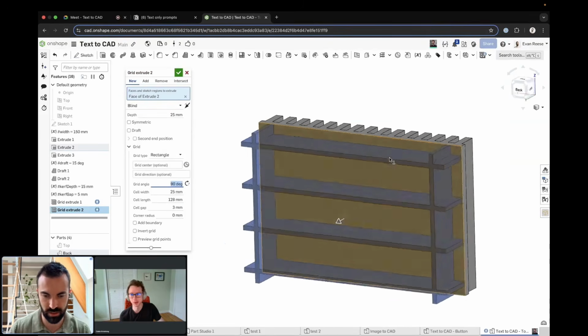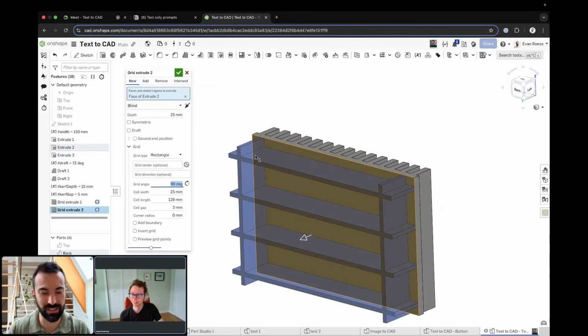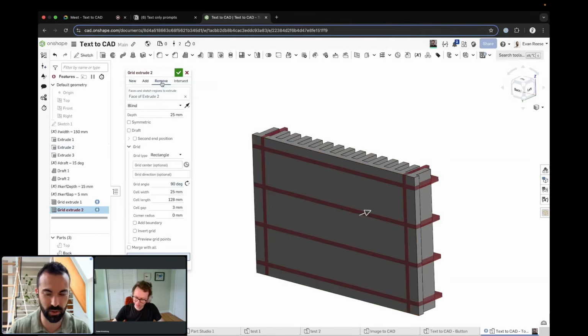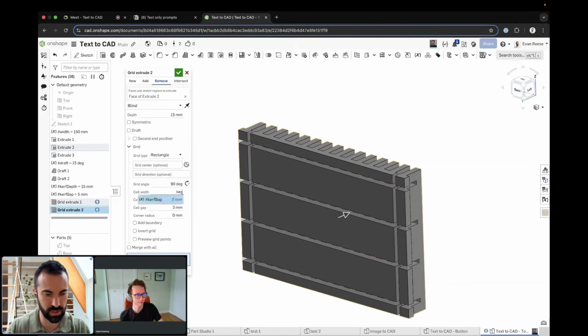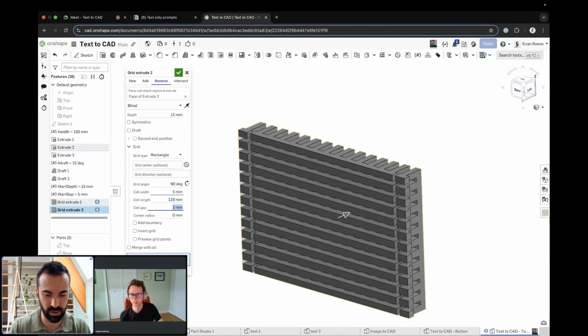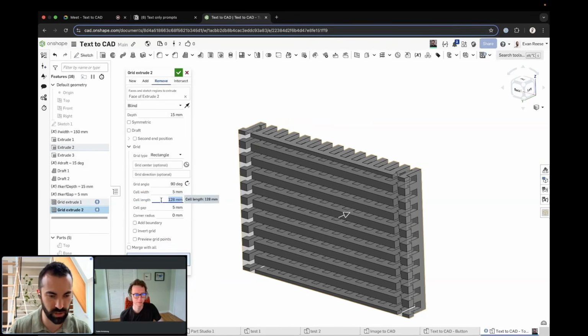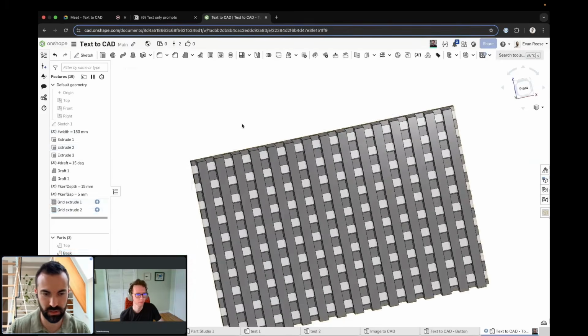Okay, here we go. My Renaissance tool has a duplicate feature option in it. Oh, that's right. Yeah, I did see that, and that is so good. Love that. Curve. Merge scope again. And here we go. Curve gap. I love how the autocomplete works because I can just type KG and it knows curve gap because it's actually looking at what I wrote here. And then the cell length, I'm just going to make it 200 because I know that's bigger. Or I can make it equal to the width times 2 or something that'll always be bigger than this. All right, so that is great.